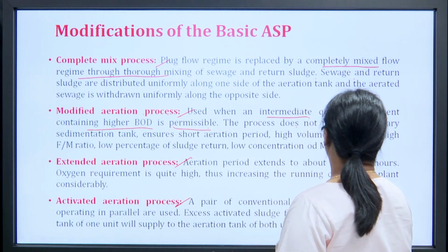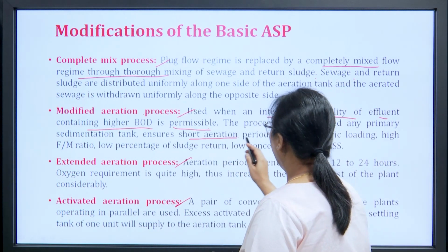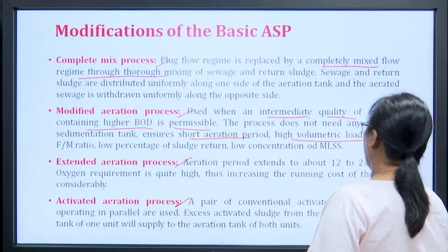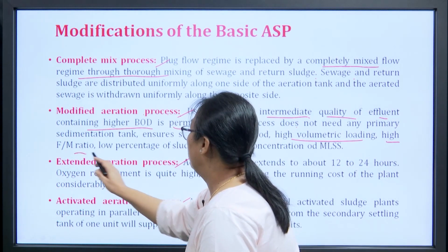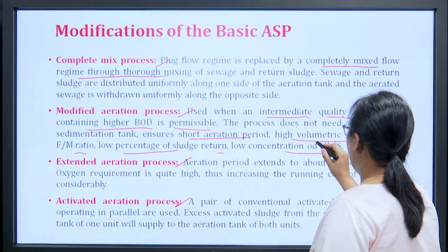This process does not need any primary sedimentation tank, ensures short aeration period, high volumetric loading, high F/M ratio, low percentage of sludge return and low concentration of MLSS.